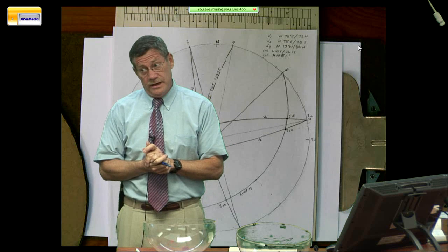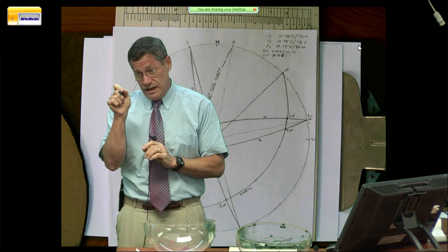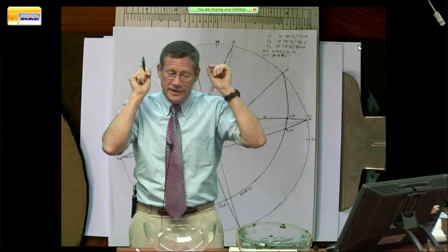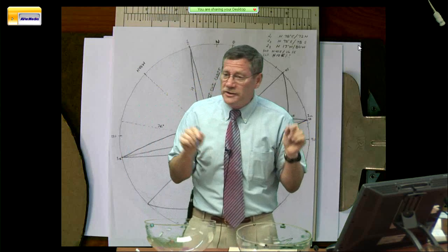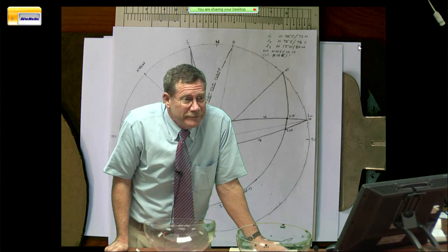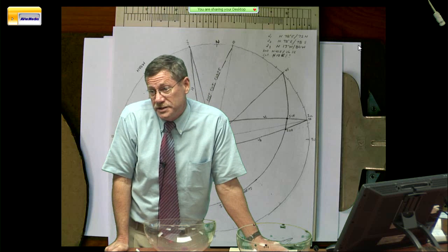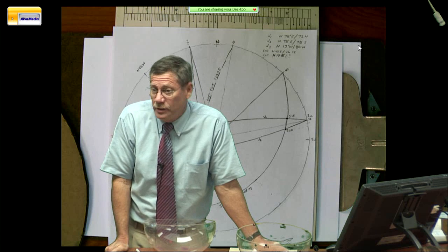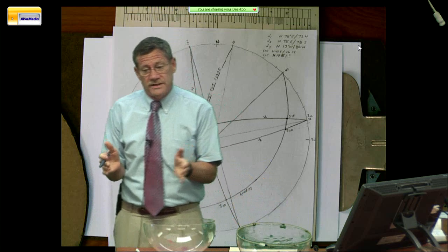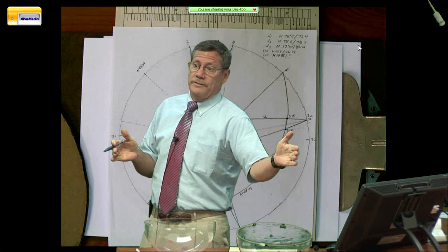So what I have to do then, joint set 3 is the one that's going to get you. Because if you put your engineering hat on, which is what we all like to do, and go, well, I'll use the average value. Use the average value, you're going to be wrong half the time. Half the time. So you decide, do you want to have the plane crash half the time, or would you rather be safe? So if you want to be safe, what you have to do is you have to say, well, this is the minimum value we measured out there.